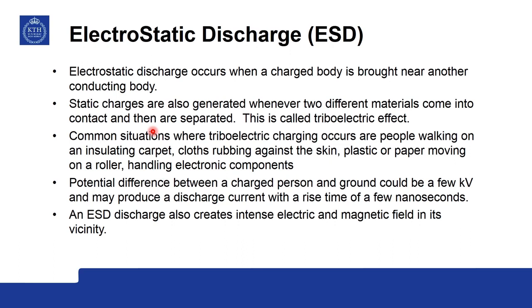Now, ESD is a big problem in the paper industry and plastic industry, whenever you have situations of material passing over rollers, because it can produce micro dimensional pinholes in the materials.